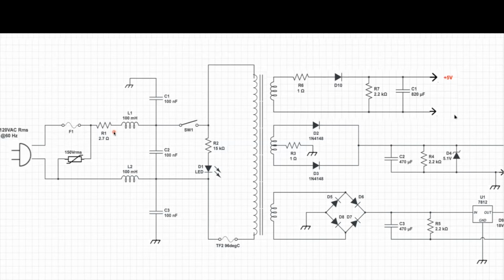Okay, so you're not wrong. If there's any excess current, you're thinking it's going to prevent that from happening. But isn't that what the fuse does? In case the fuse doesn't pop, is that what you're saying? Very good. This is a fusible resistor. It's in series with our fuse, and Moses called it exactly right. What if the fuse did not work? The main protection fuse, for some reason, does not work. So this acts like a backup for it. It's a fusible resistor in series with the main power fuse.